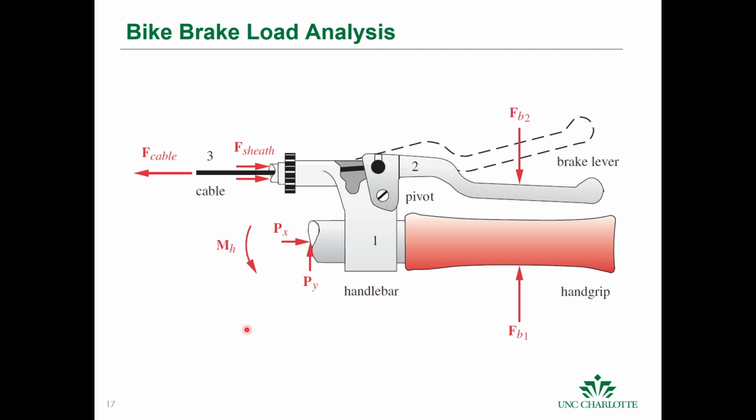I think it's case study 3A, and in this case study is just to analyze the brake lever mechanism, and it looks pretty simple, and we follow the pattern to solve this problem just like we did in statics, where we break the bodies up. So we would take this brake lever off, we would take the cable off, and then we would take this bottom part here labeled 1, and 1 would be this entire assembly here because it's all connected. The cable you see goes through the assembly.